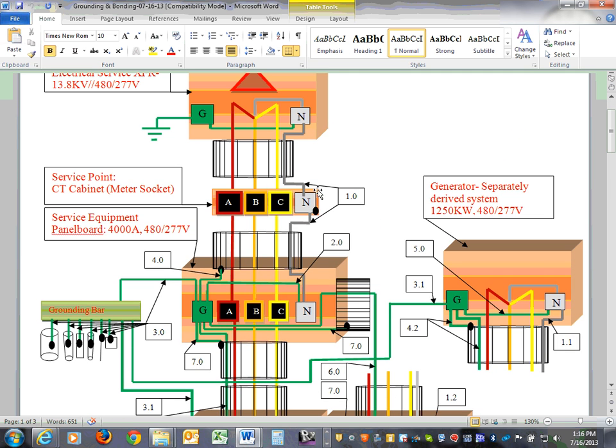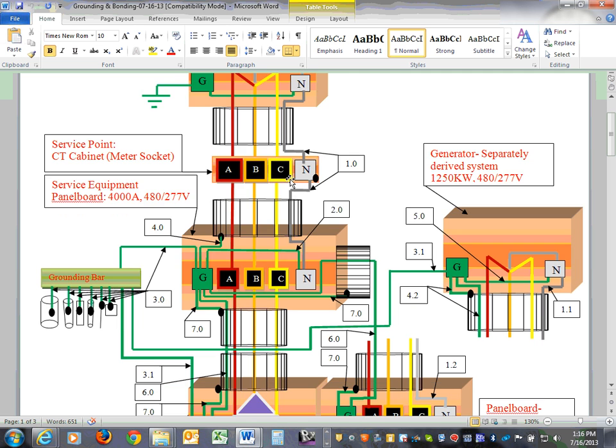We came with a grounded conductor into the meter socket. What we do is we ground the frame of the socket with the neutral. They allow you to use the neutral here to ground the box because you are on the line side of the service disconnecting means. So here's my socket. I grounded it. Can you guys see that little dot here? This is supposed to tell you that the neutral in the meter socket is tied to the frame, the box. You're grounding the box with the neutral. That's okay with the NEC code book.